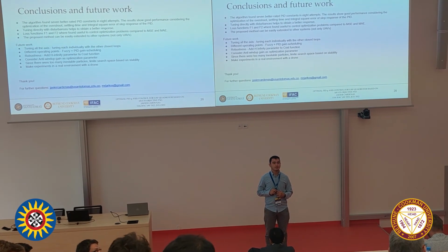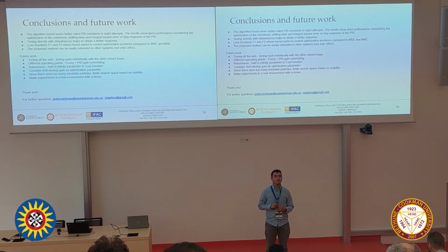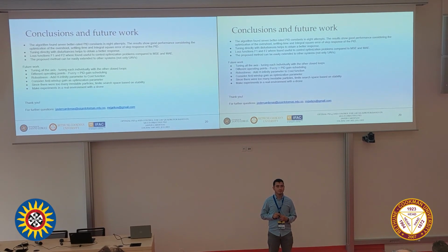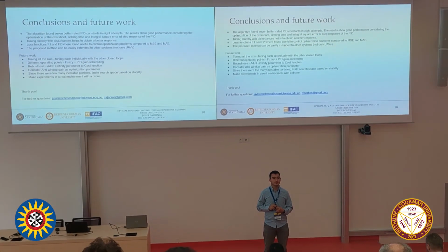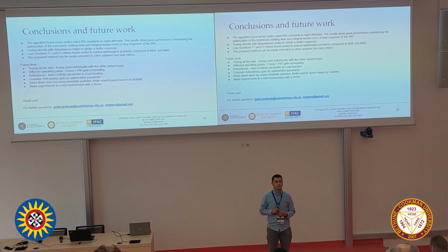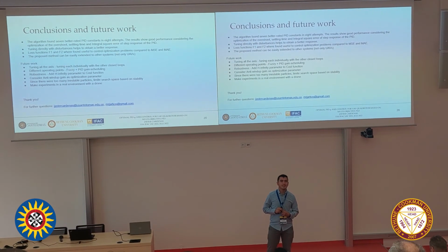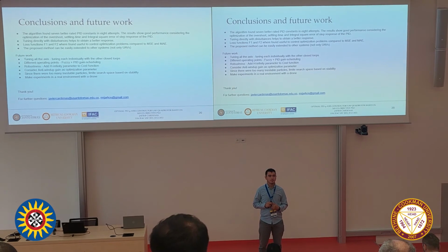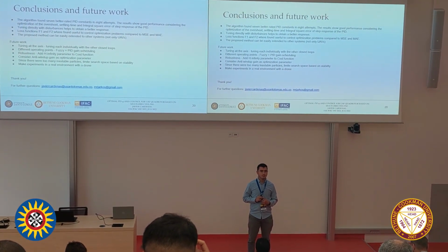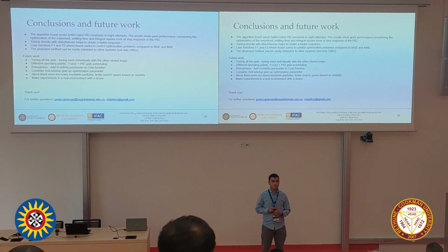But on the other side, when you apply it to the real system, which is not exactly the model, you could have a very different system behavior, because you're using a PID controller which is not really robust with respect to all the previous aspects: nonlinearities, disturbances and so on.